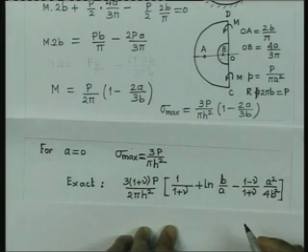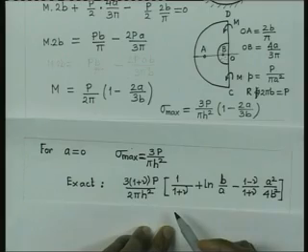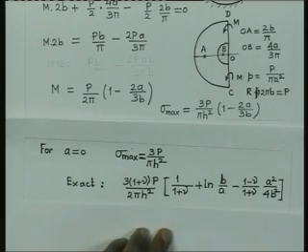exact expression. So, you can see that this is what we get when A and B are both non-zero, and that compares to this exact expression like this. There is some difference, but for approximate calculation one can make use of the formula which is derived approximately following the steps that I have talked about just now. So, this is about the circular plate. You can go on doing similar calculations for the rectangular and square plates. So, let us try to consider the case of a rectangular plate, and from the rectangular plate we can get the answer for a square plate.